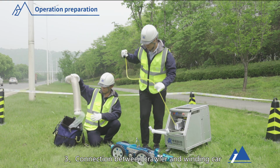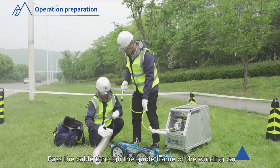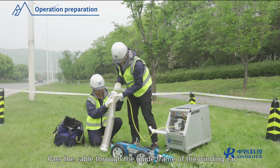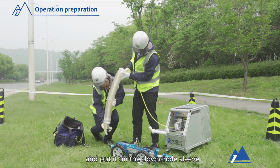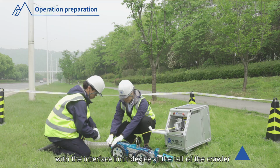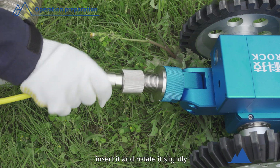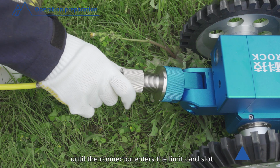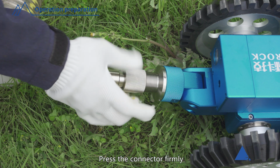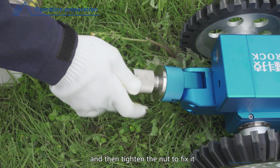3. Connection between crawler and winding car. Pass the cable through the guide frame of the winding car and put it on the downhole sleeve. Align the connector of the winding car with the interface limit device at the tail of the crawler. Insert it and rotate it slightly until the connector enters the limit slot. Press the connector firmly and then tighten the nut to fix it.